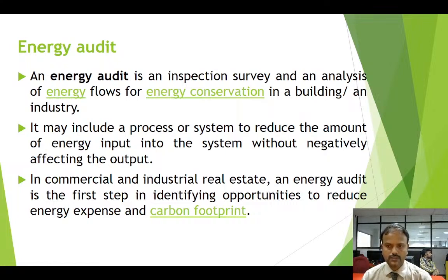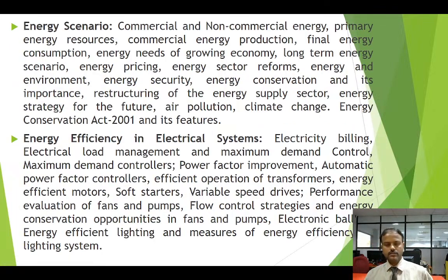In most industries, we can see that the transformers and the induction motor are the main load, wherein we can improve the power factor. Once you go through the inspection, you will come to know the operating characteristics or operating parameters of the induction motor by looking at the data. So either you can take a preventive measure or a required measure to improve the power factor, or go for replacement of the machine. By that we can conserve the energy, reduce the energy expense and carbon footprint. So this is the introduction to your energy conservation audit, and this is the course content.